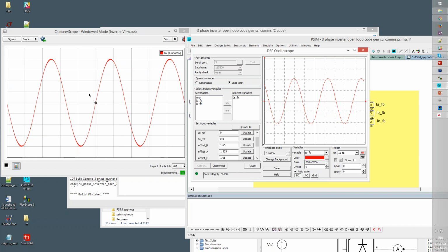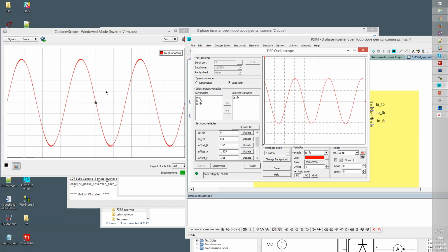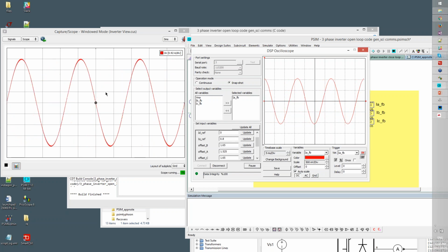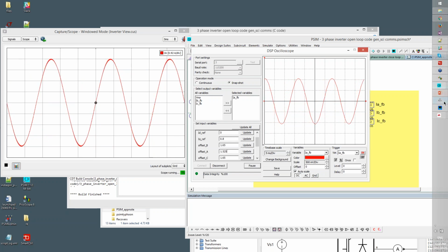The next thing I'm going to do is we can see our signal over here is 0.92, and that is times 4, right? 1, yep, 2, 3, 4. And what's that math? 4 times 0.92, 3.68. So we're going to need to see 3.68 over here. So to check that, I'm going to change the offset here to 3.68, and we'll see that signal went away. And now I'm going to adjust the gain to increase it.